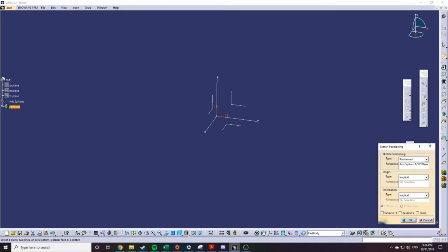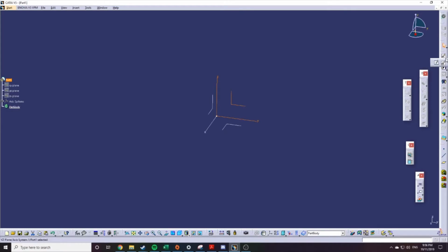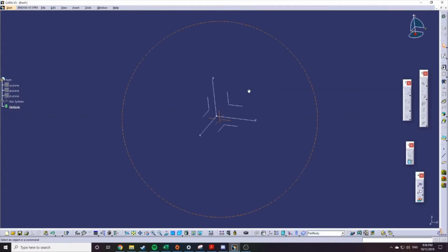So you'll see here, I've gone for a position sketch. The difference between a position sketch and a normal sketch is a normal sketch will just assume your vertical and horizontal and what it's mounted to. This can be useful when you're using an axis system, and generally it will give an alright answer, but if you want to be real proper and learn the skills correctly, a position sketch is very useful as it allows you to control everything. So we go to position sketch.